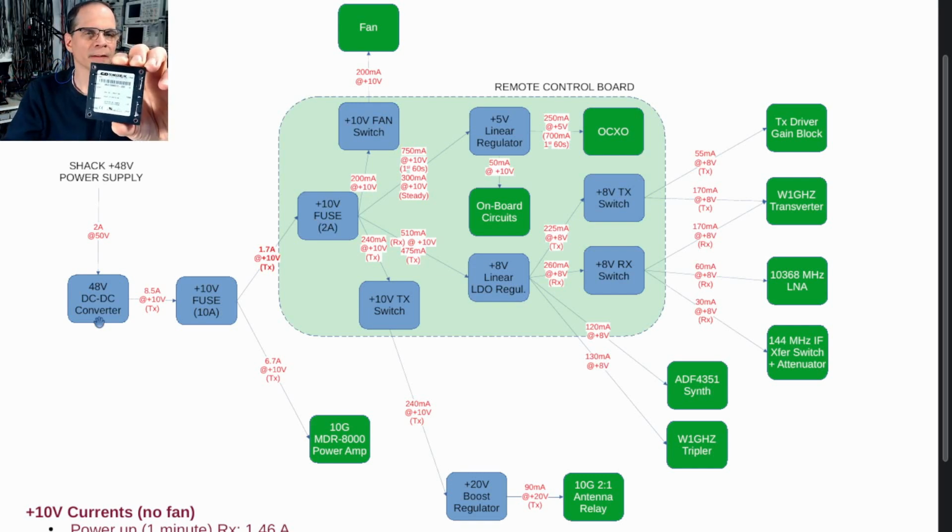This is it. Okay, it's a small cube. It's what we call a half brick size DC-DC converter. It's a C&D Technologies model VKA 150 MS12. It's a 12 volt DC-DC converter. It can take from 36 volts to 75 volts in, and it produces 12 volts out, and it can be trimmed down to 10 volts. That's the nice thing about it.